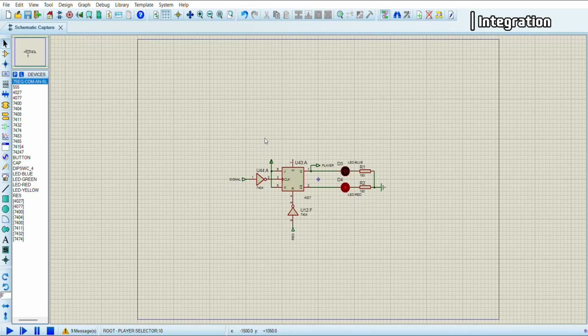When it happens like that, the memory gets updated. As we have used a NOT gate, when the signal is 0, normally when we do nothing, the clock is always getting a high value, because the signal normally remains 0.